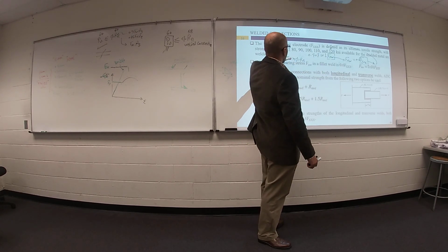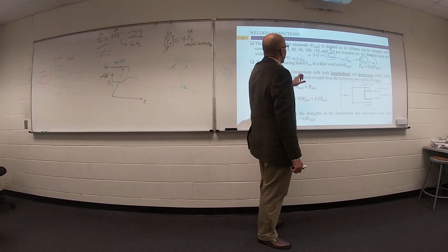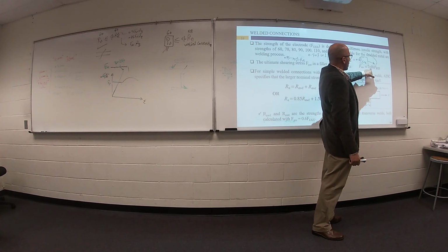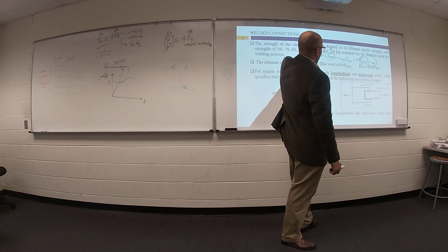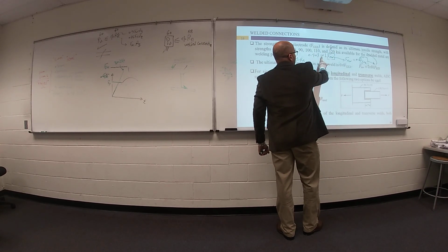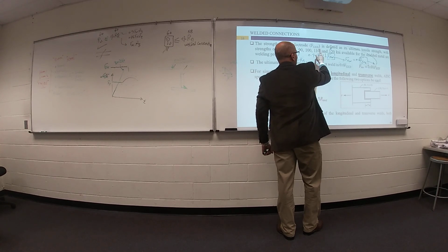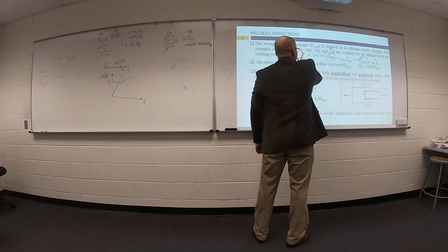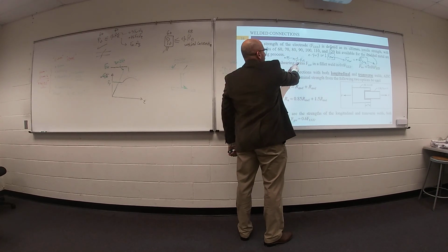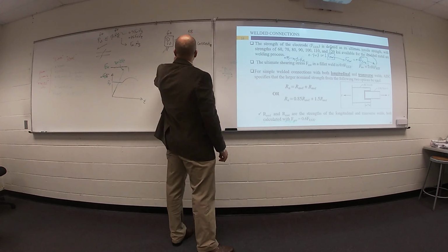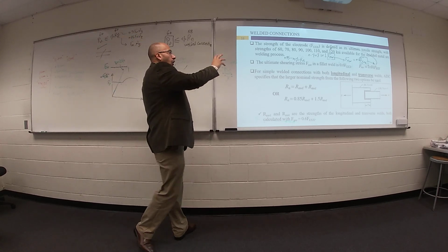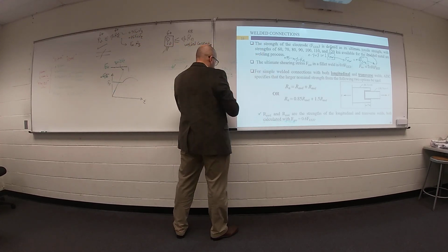rod I will use. Which one is available to buy. Then I can figure out what is the value of FNW by multiplying 0.6 times which value. Then go ahead and use this value by multiplying it by the size and the length of weld by 0.707. You can get your nominal strength. Multiplied by Phi, I can tell you what is the design strength, then make your comparison between the factored load and design strength. All of these processes only if